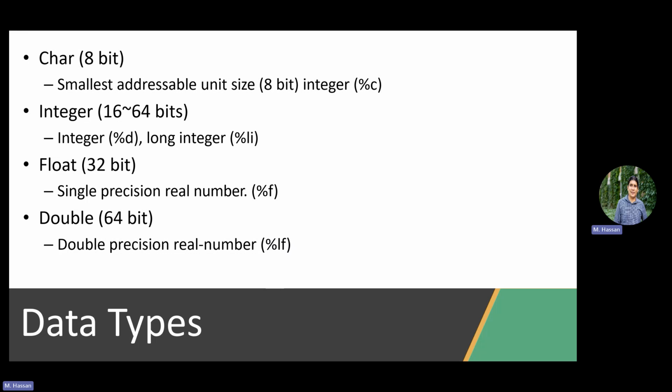Now, data types in C, why is it important to review in embedded? Because your friend said I need to be very well optimized for memory. Assume I want to access certain bits in a register that I know will always be only 8 bits. It doesn't make sense to define a variable that is an int, because your int can be 32 bits, but you're only going to use 8 bits. So you're wasting 24 bits for no reason. 75% of your memory is wasted for this variable. So you need to be very aware of how you define your variables and types in embedded C compared to C.